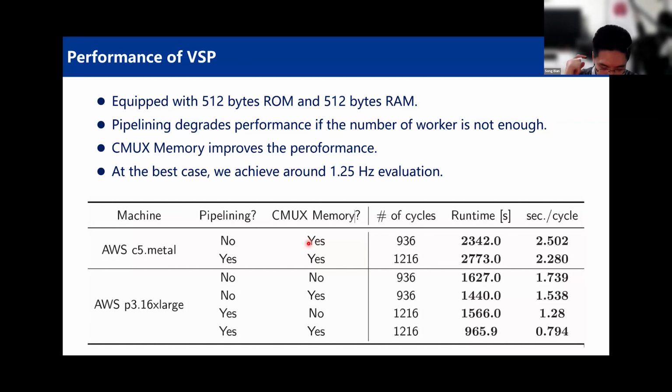So if we execute an instruction, whatever it is, add, multiply, or something, we will always write to every address of the memory to make sure that the server does not see what kind of address we wrote in. So combined with the ciphertext expansion of encrypting bits, we designed a 512 bytes ROM for storing programs and 512 bytes RAM for storing intermediate results.